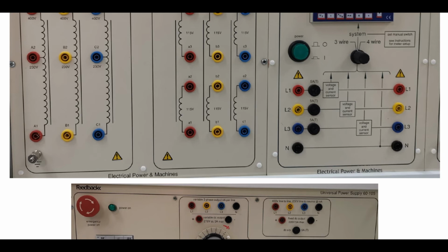We take the last terminals of each one of the windings and connect them together. By doing so, I'm making my Y connection. One wire comes here, and the other wire connects this terminal to the other one. So these 2 wires create what we call the Y connection. That's the center point that connects the three windings. The same thing will be done at the secondary side.